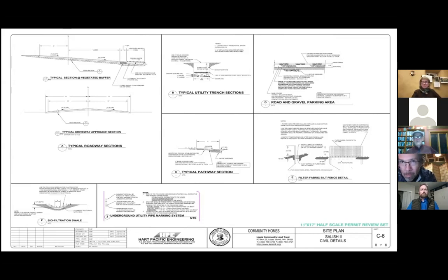Exactly. And I found that it's actually more effective than the silt fencing. Like you say, if the silt fencing is put in correctly and buried in, it's a big impact. Whereas the straw wattles, like I said, just kind of compost in. And on a construction site you always have room for that. These are just details that you'll see.